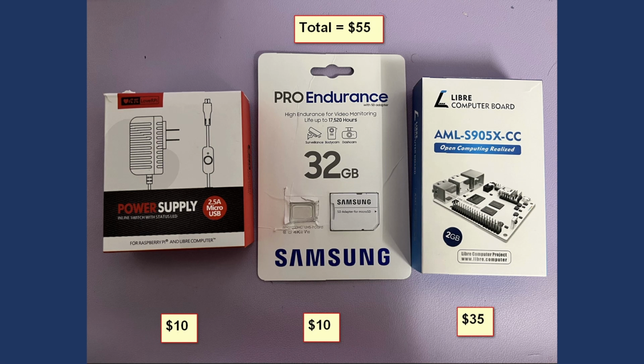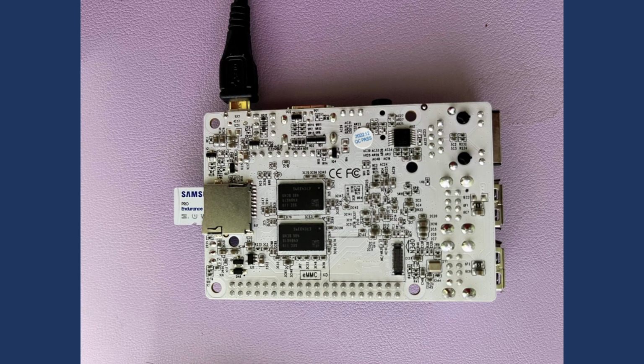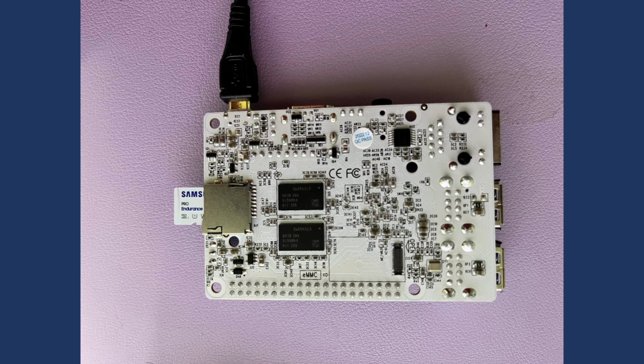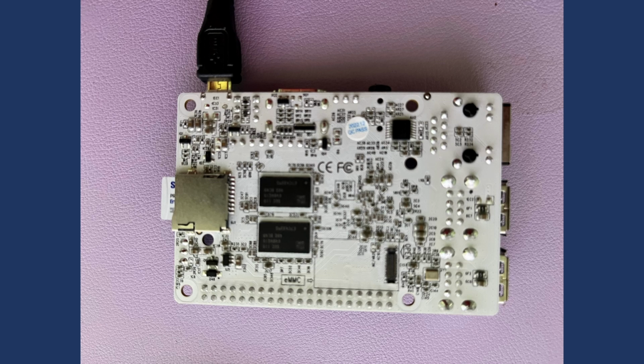Let's insert the micro SD card inside the ARM based hardware, because you need to be very careful. I'm showing you the ARM based hardware upside down. So this is how the orientation of the micro SD card should look. Remember, it is not pressed yet. You have to insert it and then press it. When you press it, it will sink a little bit inside, so it will go from here to here. Okay. So let's try to install Ubuntu on this piece of hardware.